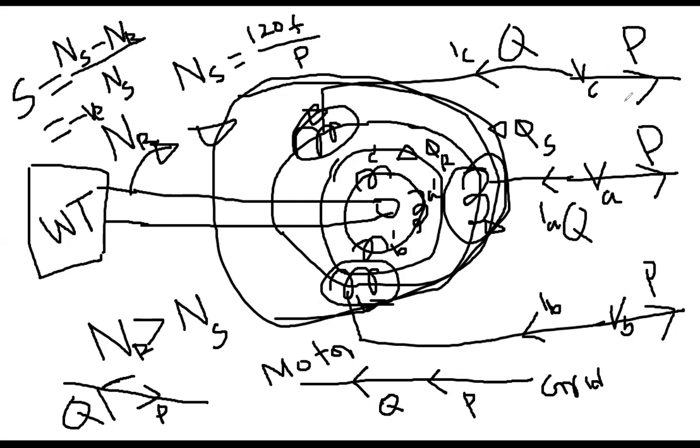So what you have to do? You have to put some compensator at the terminal. Capacitor, exactly. You have to put a capacitor. That will compensate the reactive power. So that is the necessity of putting a capacitor at the terminal of the induction machine. Everybody, I will be asking you this question: why is it needed to put the capacitor at the terminal of the induction machine?